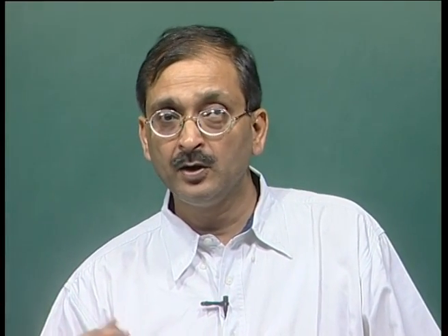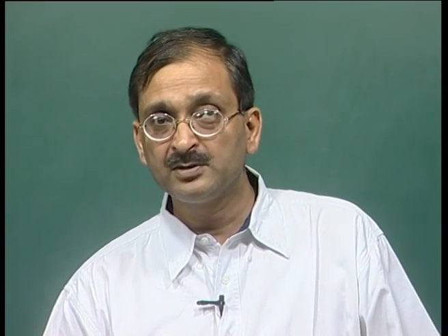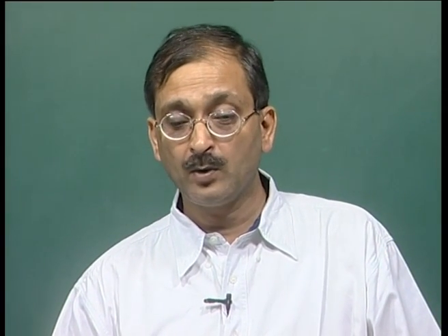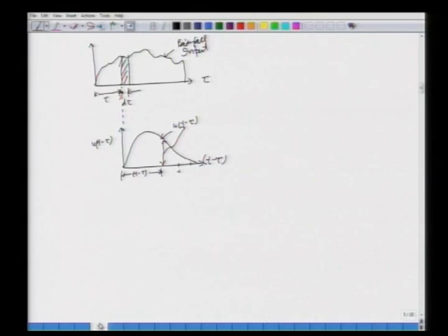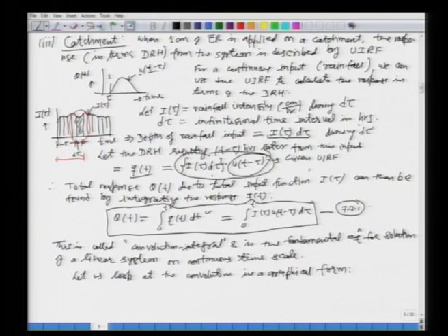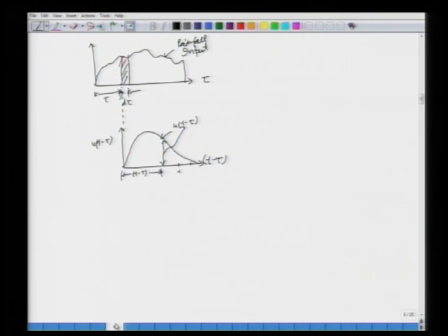Well, the convolution integral uses this unit impulse response function and applies the series of these rainfalls, all right, small strips, and convolutes all of that through the catchment to give you a combined response as per equation 7.2.1, okay, which is this equation. Okay. So, we are looking at the expression of this equation 7.2.1 graphically. All right. Okay.